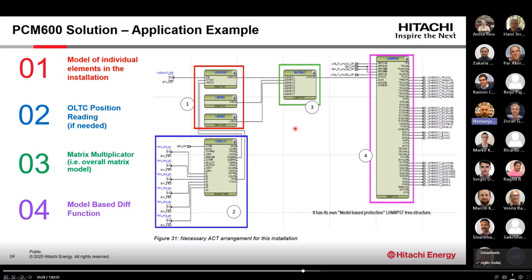The idea of the model base is definitely something that can be adapted to be used for that. Yeah, it can be extended, of course. As well, what we have done in the PST, we have made a separate model-based section. If you are familiar with 670, we have current protection, voltage protection, differential protections, impedance protections. Now we have made a new category, model-based protections, and all these function blocks will practically be lying there. Therefore, in the future, depending on market responses, we can expand this.